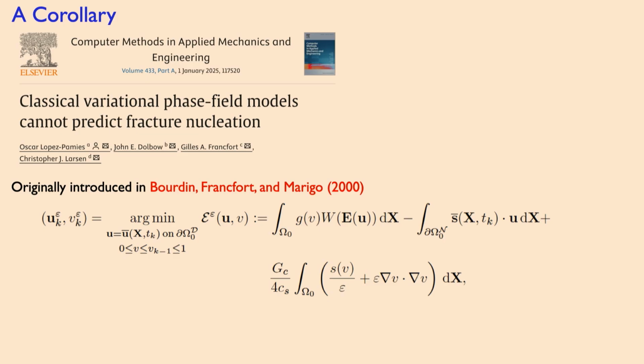And what people have been trying to show is setting the regularization parameter epsilon to a material property, thinking about it as a material scale, and tuning it to your uniaxial tensile strength. You can do that, but then you're going to miss the rest of the surface. And that information is really important.